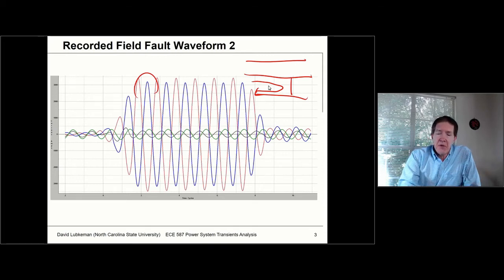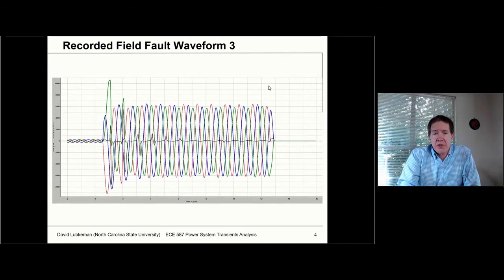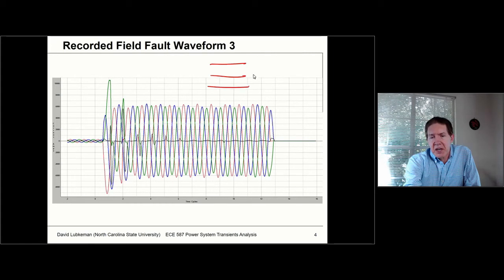And then for a three-phase fault, which is probably more the scenario you initially did circuit calculations with when you started learning power systems, we have all three phases connected together. In this case, in steady state, we're going to get the same current magnitude per phase. You're just going to be off by plus or minus 120 degrees.